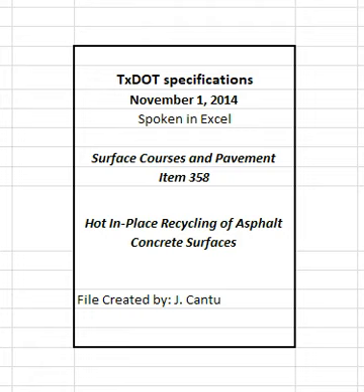2.3 Aggregate. If the process requires additional aggregate, furnish aggregates to meet the requirements shown in Section 358.4.2, Mixture Design. Use aggregates meeting the requirements of Article 340.2, Materials. 3. Equipment. Provide required or necessary equipment in accordance with Item 320, Equipment for asphalt concrete pavement.